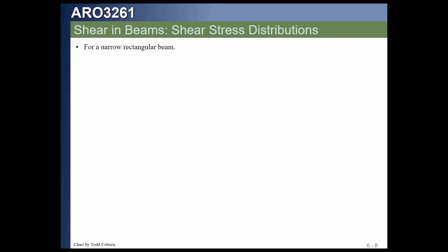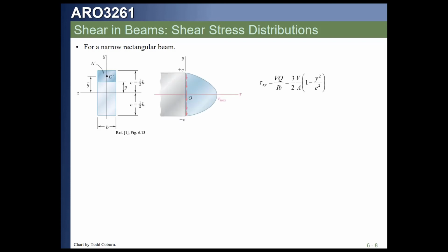So because we have our equation here, if we look at our shear stress distribution, remember we can calculate the shear flow at any point by just taking the Q of everything above it. So our basic equation is VQ over IB. If we want the shear flow right here, our shear stress equals VQ over IB, where B is the width, right? You can see that the width, B, is the same from top to bottom for this segment.